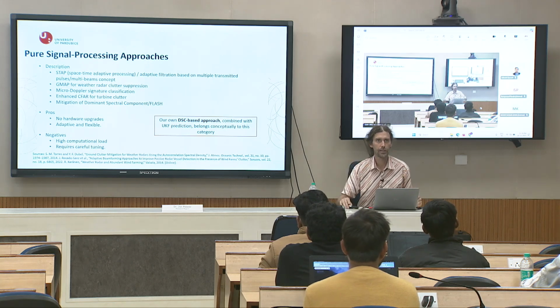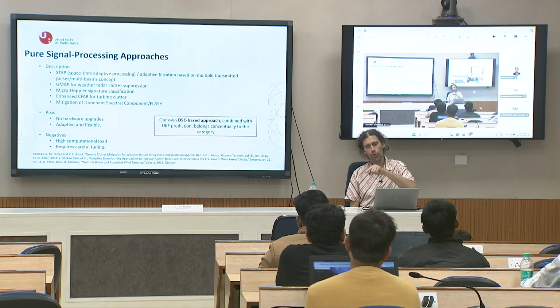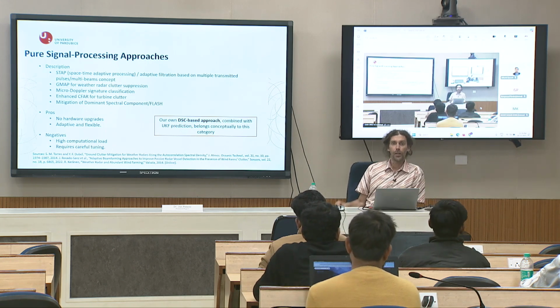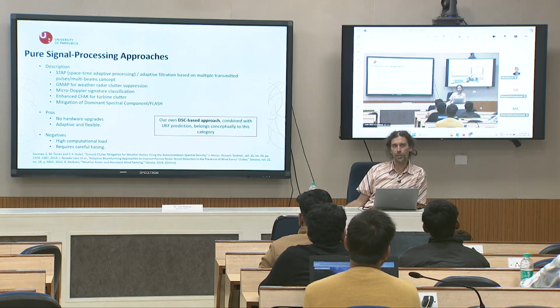And this causes microdoppler shifts. So it is small changes in Doppler shift. It is like a sawtooth, changing something like this. And what is interesting, this microdoppler is hard to identify. Why do you think? You need a really big resolution in Doppler, because it is such a small shift. So you need really good resolution in Doppler. But if you are able to identify it, then you can even use this information for classification of the target.